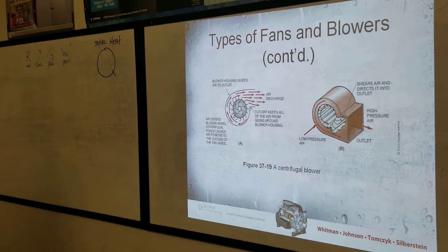This is the type of blower we're gonna use for ductwork. This works well for ductwork. The propeller fan will not work in ductwork. You just can't push against static pressure. These can push against static pressure.